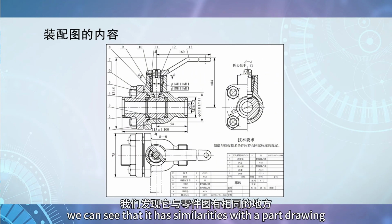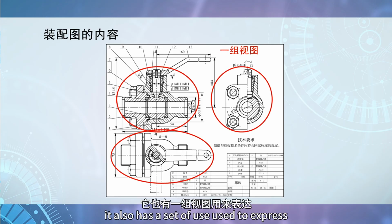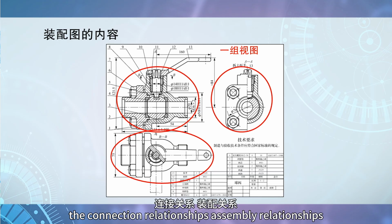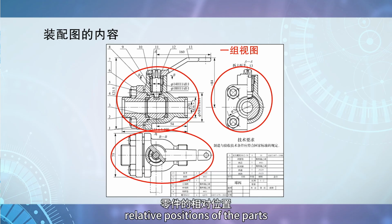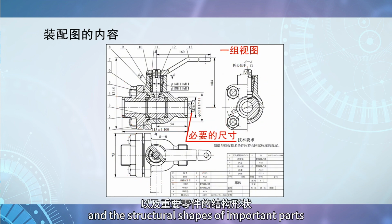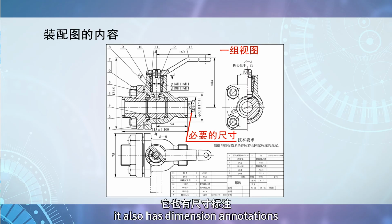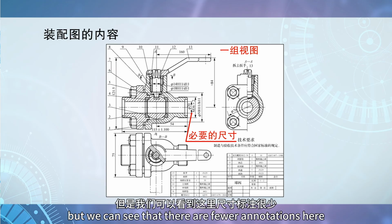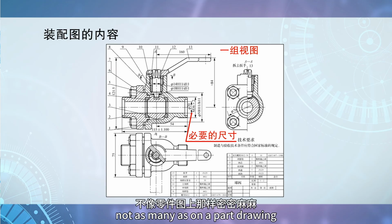We can see that it has similarities with a part drawing. It also has a set of views used to express the working principle of the machine or component, the connection relationships, assembly relationships, relative positions of the parts, and the structural shapes of important parts. It also has dimension annotations. But we can see that there are fewer annotations here, not as many as on a part drawing.